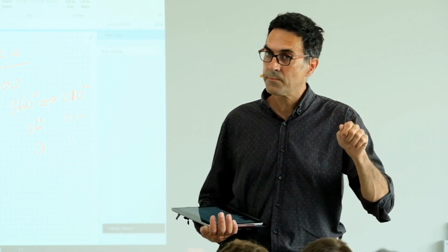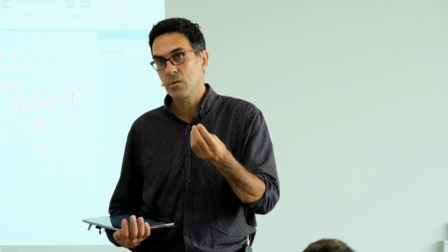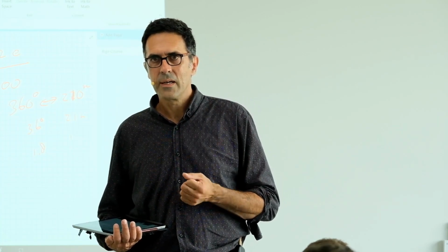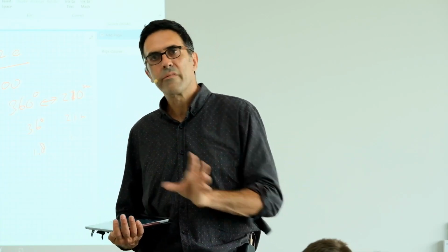The second part is that indeed everything we're measuring is relative inside such a data set. So there is a reference point and there is a reference epoch. The reference epoch is just the image that we start with, or that we choose to be the center of our data processing. It could also be the latest, but we need to make a choice. So where in time do we start? And the reference point is the point of which we assume that the elevation is known and the displacement is either also known or zero. That is maybe why you asked the question: if you make an error there, it will affect all the points.